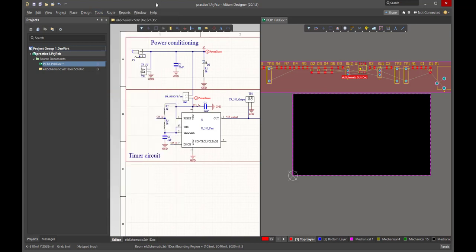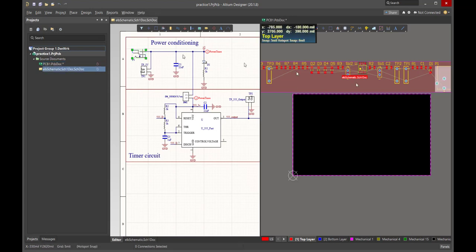The reason that's so valuable is when I click on a part in my schematic, I will see that part in the little room with all those parts. For example, let's grab the power jack because we're going to move that over to the upper left corner of the board. We'll highlight it in the schematic. And look, over here it's highlighted in the printed circuit board.